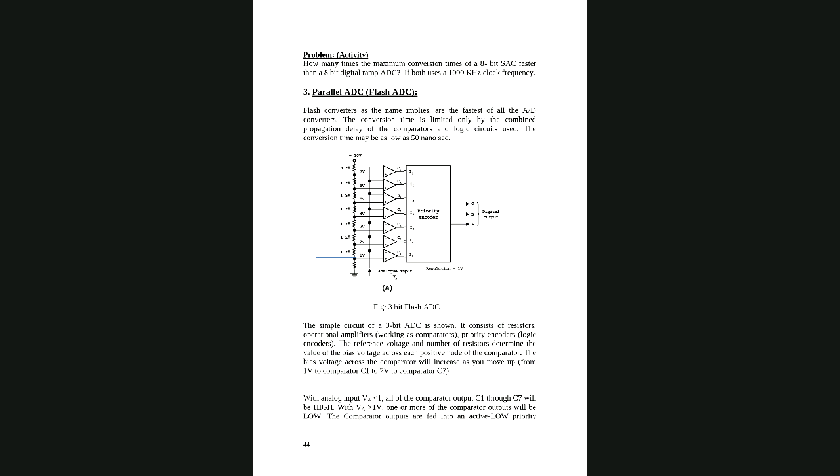The voltage divider rule says take the resistance here, divided by the total resistance. Here it is 1 kilo over the total resistance of 10 kilo, times 10 volt, because the total is 10 volt. So how much did you get? 1 volt.